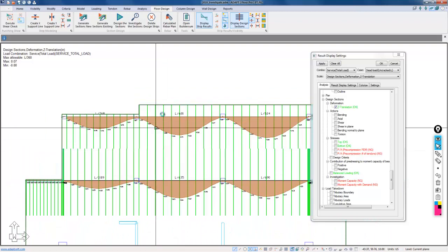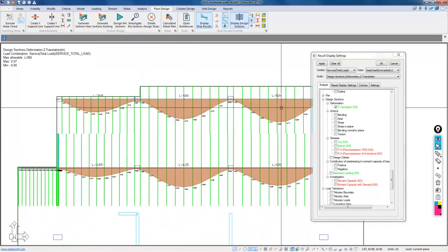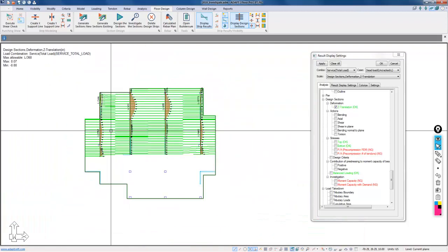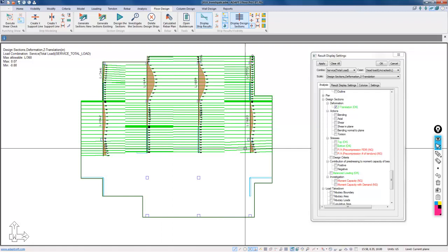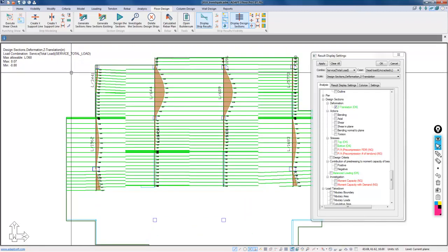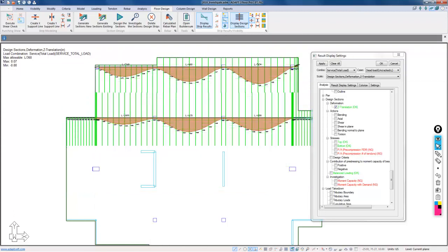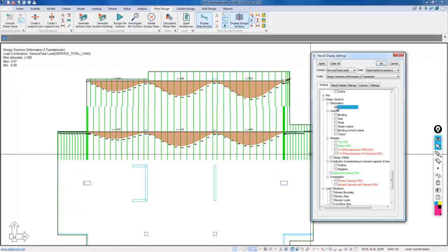So that's a quick check we make for those deflections in the slab along the strips. And you could do that actually for both directions here. This back here may not even pertain to anything because it's just a half span. It doesn't really mean anything in terms of what's happening in this bay here. But that allows you to look at a quick deflection check.